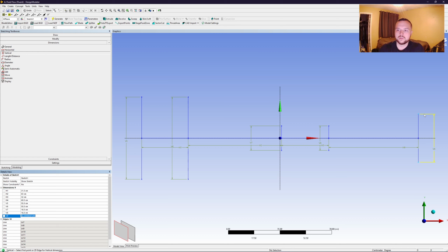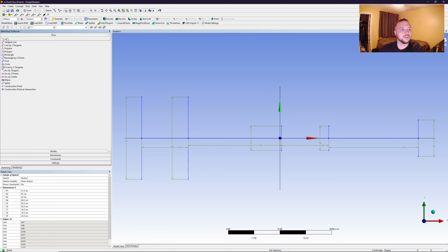However, you can also, if you just measured the beginning of the diffuser, which is also the end of the test section, and then the end of the diffuser, you can input those and then it'll automatically go to the proper half angle. So I need to make sure that it's at each point. The end of each line terminates at each of these top points.